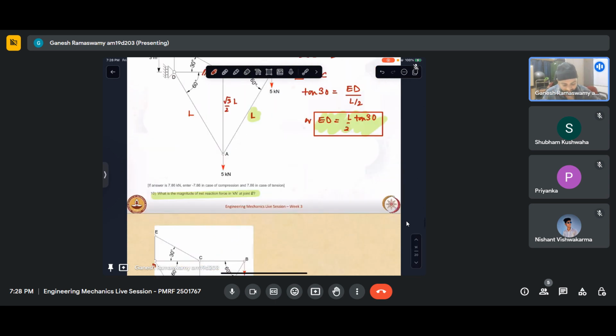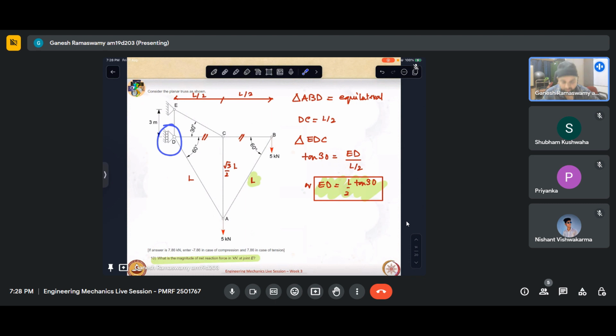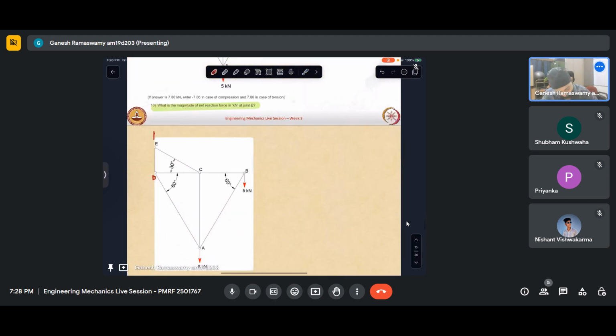And we can see that we have a roller at joint D and we have a pin support at joint E. So there will be a vertical reaction, call it Ey. There will be a reaction like this, call it Ex. And then at the roller, there will be another Dx. Let us consider this to be the X direction and this to be Y.